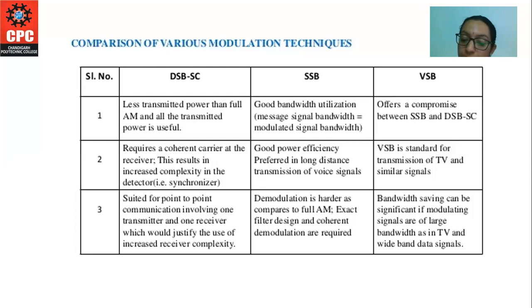We know that in single sideband transmission, the carrier and one of the sidebands are removed from the signal. It is quite possible that the removed sideband is replaced with another sideband carrying information created by modulating a different input signal on the same carrier, which ultimately results in independent sideband transmission.